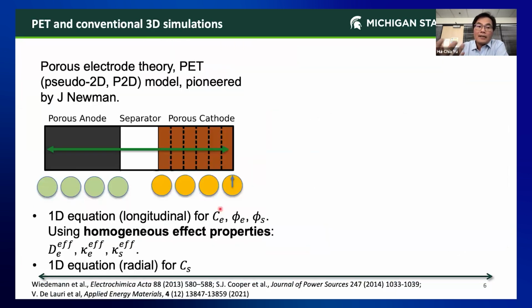If you really want to understand the electrochemical process, you would like to do simulation out of that, right? Because the geometry is very complicated, currently the prevailing model in the community is called porous electrode theory. The idea is that because the microstructure is very complicated, they just homogenize the entire microstructure, assuming it's a uniform medium with effective material properties, for example, the effective conductivity of the porous media. Then in the thickness direction, you are solving a 1D problem with all homogenized effective properties.